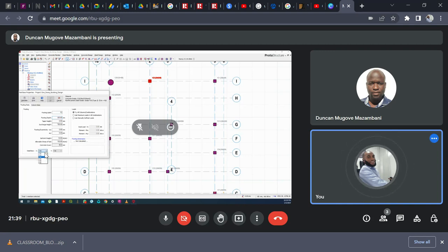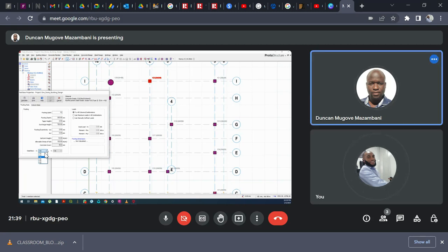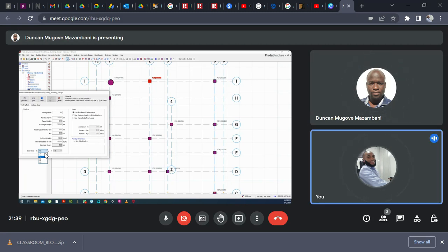Choose them there. Now for a one-story building, the first thing that should come to your mind is the Y12. Okay, if it's not checked here, click on cancel and go and assign it in your material property. So just cancel, then go and assign the rebars for foundation.